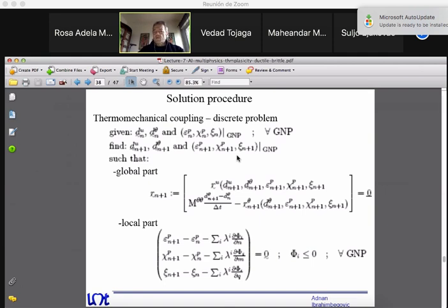So you can see the typical approximation for the heat transfer problem here. You have the capacity matrix times the nodal temperature rate, approximated with a derivative here, and then you have the contribution from the heat flux. It could be a nonlinear function of all of these, including the plastic deformation and so on. If you're going to take into account plastic dissipation and stuff like that, that means you need plastic deformation and hardening and so forth.